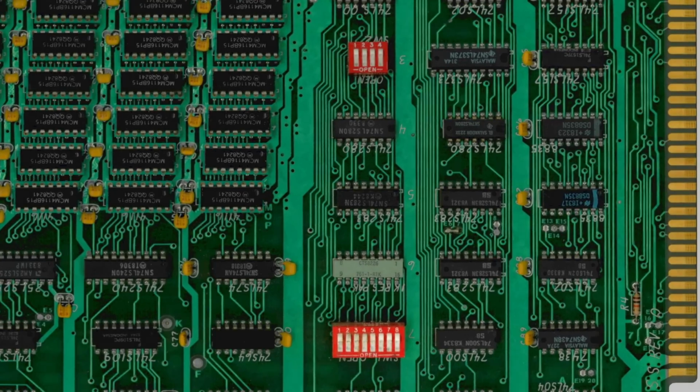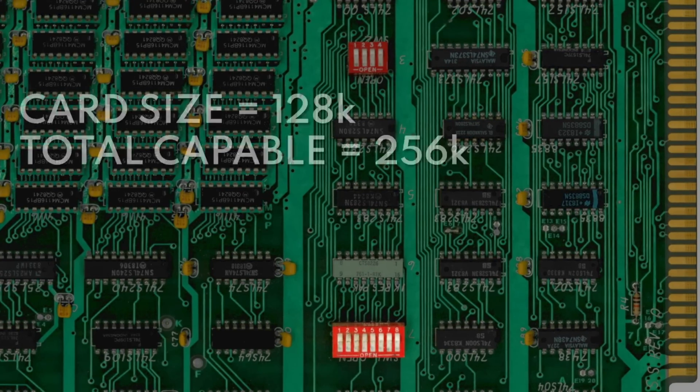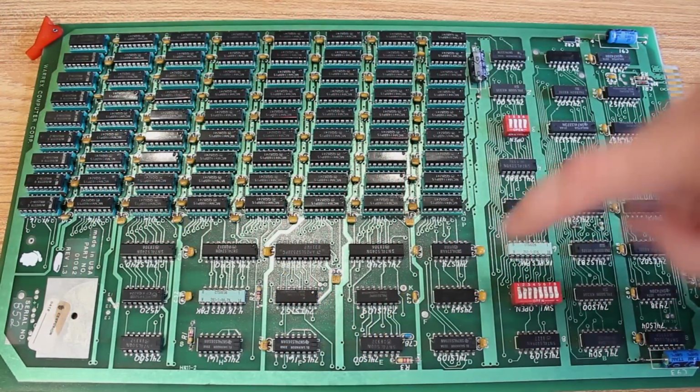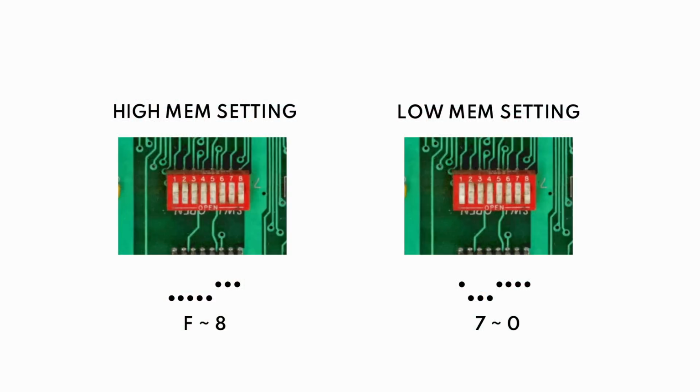Now, the 8 position dip switch down here is used for multiple memory cards. This is a 128K memory card, and the machine can support up to 256K. So we just kind of select the space that it lives in with this. And with the dip switches in the position that they currently are, this one says that it's in the space from 0 to 7. And so if we put the second 128K board in, it's going to be in the position from 8 to F.